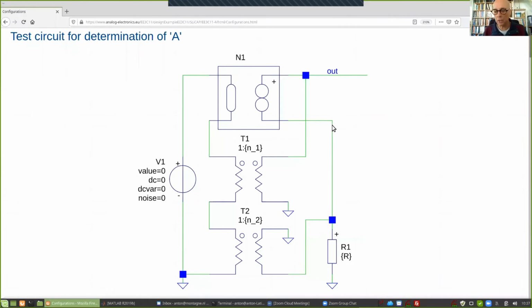It is realized by making both parallel feedback at the output and series feedback at the output. Series feedback, we measure the current, convert it into a voltage, and here the voltage is compared at the input. So we have voltage to current, voltage to voltage and voltage to current conversion of this amplifier, which means it is voltage in and a characteristic output impedance.